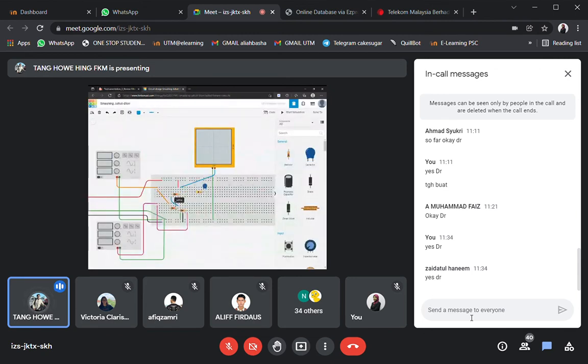Okay, so the output from the op amp, which is the summation, is here. So this is the output, and therefore I just connect it to here. Okay, output going to the input of the resistor, and then the output from the capacitor needs to go to the ground. So the ground is green color.